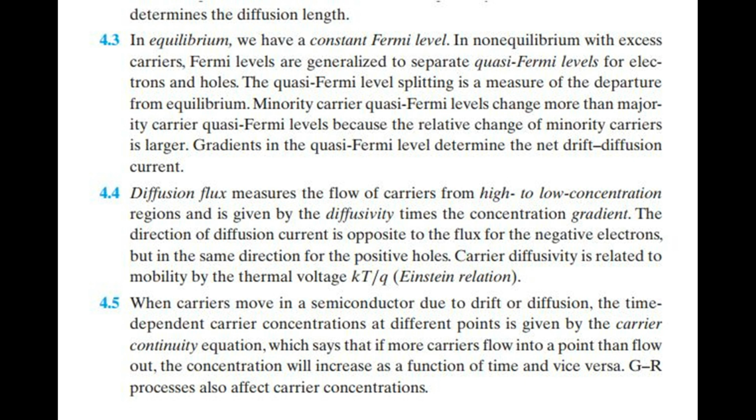When carriers move in a semiconductor due to drift or diffusion, the time-dependent carrier concentrations at different points are given by the carrier continuity equation, which says that if more carriers flow into a point than flow out, the concentration will increase as a function of time and vice versa. GR processes also affect carrier concentrations.